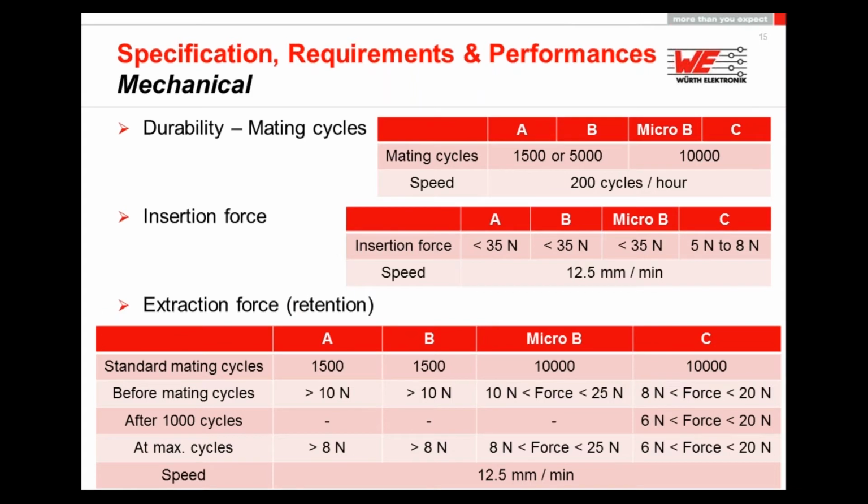Okay, what you can see here is the pinning, and you will find in the table the graph of the different power supplies, what every pin is able to handle. And here we can see that they are distributed, so they don't all have the same current rating that the pins are able to handle. So 0.25 amps is for signals, that's the maximum rating, but then for the power delivery mode, up to 5 amps we are able to handle with those pins.